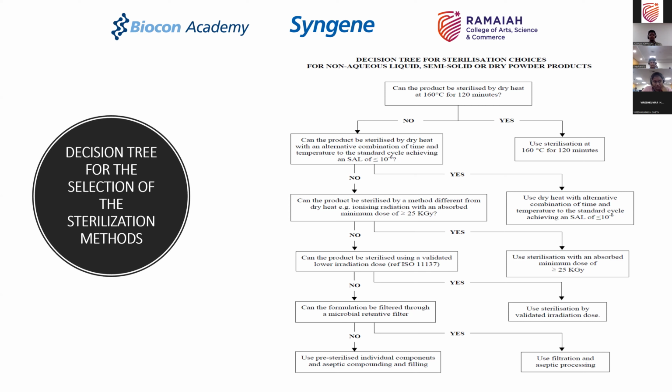There are other techniques of doing it. Sometimes you directly take a slurry and subject it to freeze drying in a sterile freeze dryer or a bulk freeze dryer, or even an active freeze dryer. These are other examples where, once the freeze dried powder is ready, you just remove it. A lyophilized powder is ready, you remove it, and then you subject it to filling.